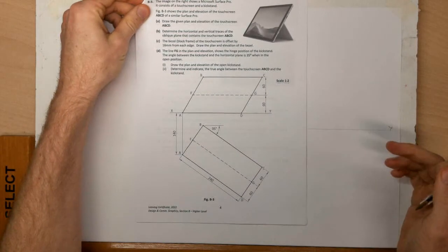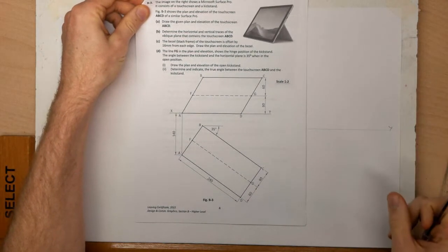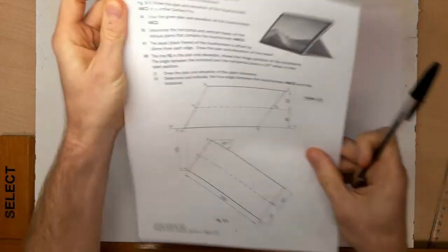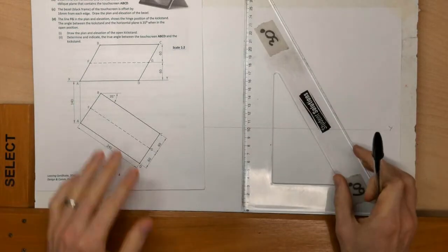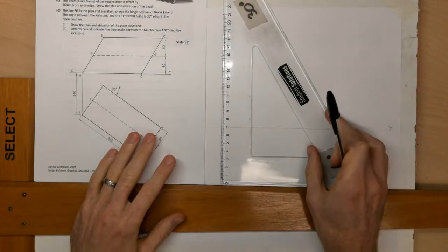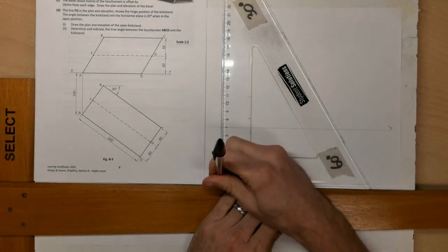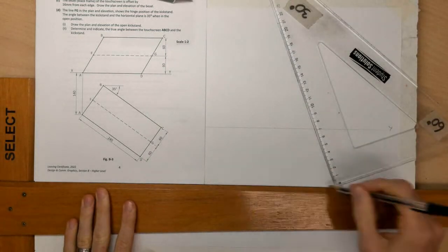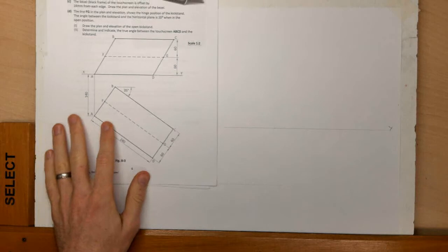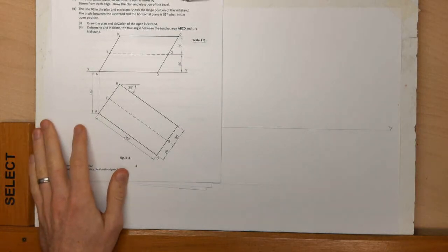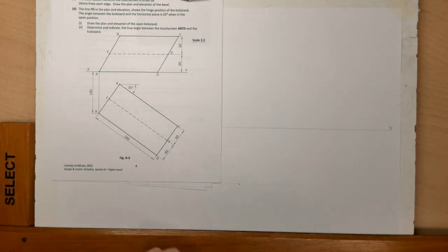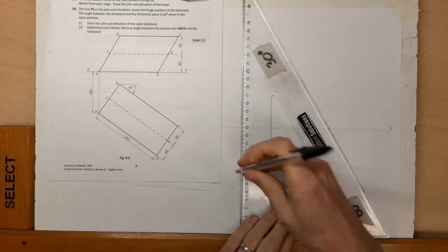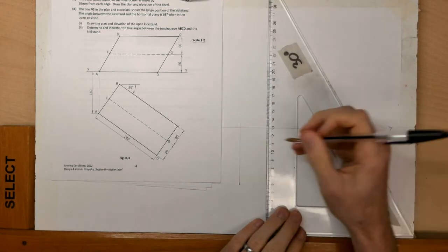So just to give this enough space, I'll come down 150, plenty of space there for my XY line, and I'm going to begin drawing my plan and elevation. So like it says, down 70 to A, so A is going to be somewhere at that level, and I'm just going to pick a point here and draw vertically up there. That's the corresponding point A.